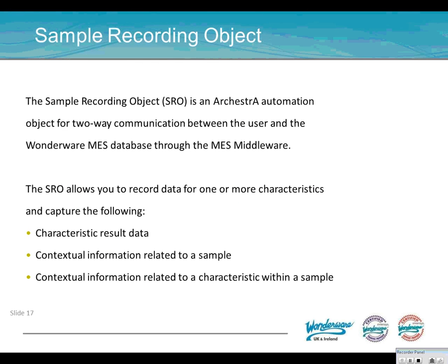And then we have a sample recording object, which is an additional template object which is included within the system platform application server environment to enable two-way communication between the user and the Wonderware MES database through the MES middleware. So this allows us to do the automatic recording of data for the various characteristics which comprise the sample of information that you're trying to collect, and also allows you to apply contextual information either to the sample as a whole or individual characteristics within a sample.